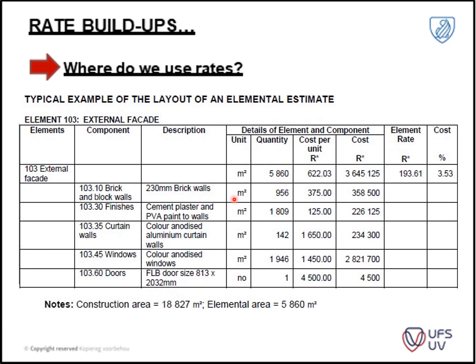Okay, so you will see brickwork is measured as a per square meter rate, but you might have the instance where you have to include your reinforcing or brick force, which is usually measured in meters and with the size provided for it. So you need to calculate how many layers of brickwork there is, and then it is translated into your rate and subsequently your cost. Something also just to note here is your quantity to get to your element or component. So the calculation that we've got here is the element that you use for your brickwork.